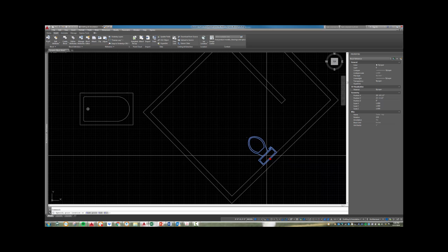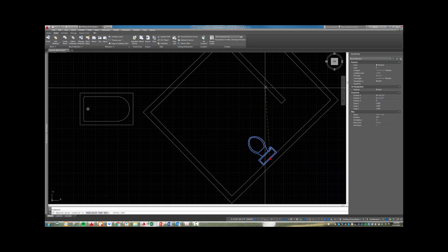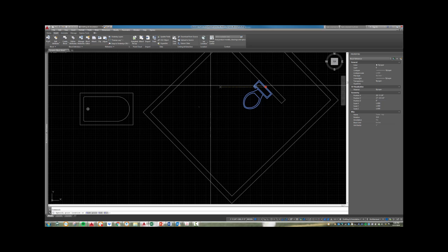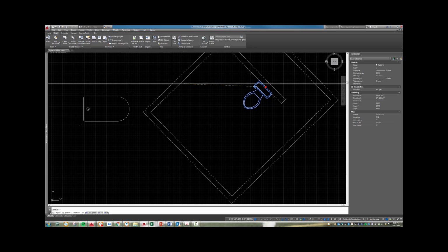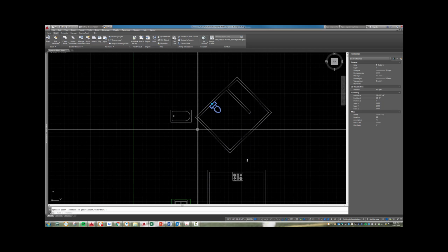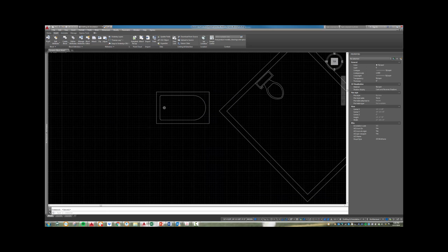So when you move it, the direction you come into the wall from matters. I'm going to turn my ortho off. That was what my problem was. So if you watch as I pick here, if I come from the outside into the wall here, it's going to face, oh there it goes, it flips over. Now, see, it wants to do that. If I come from the inside, it's going to want to flip towards the inside of the room. So again, that's the alignment portion.